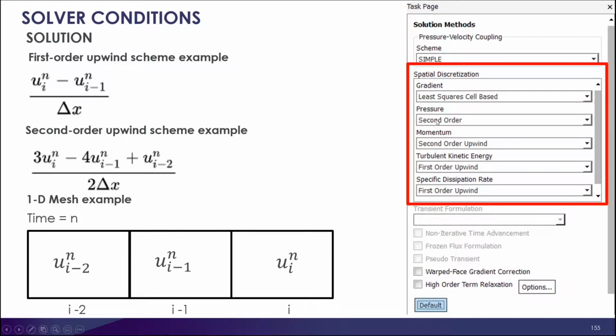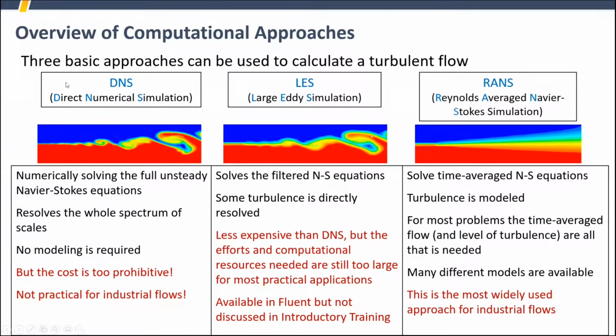Okay. Now remember what I said about direct numerical simulation. So direct numerical simulation, if I can take us back there very quickly, is our turbulence modeling when we're looking at directly modeling all the turbulence. One of the things we have to do for a proper direct numerical simulation is have higher order spatial discretizations, upwards of third and fourth order, because that gives us higher accuracy and allows us to pick up more with less elements. Okay.